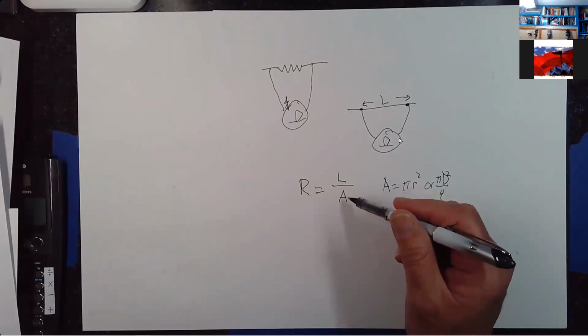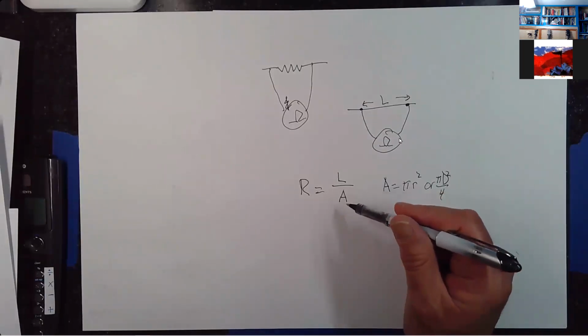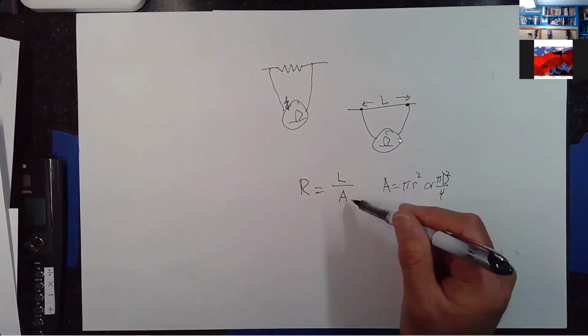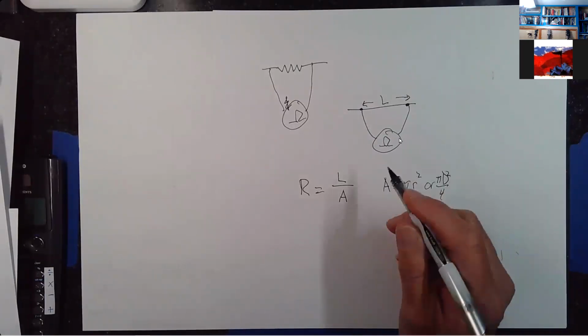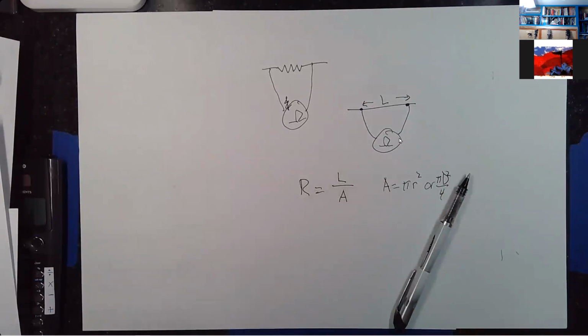This is the reason that they make wires thicker and thicker. If you've got 14 gauge wire in your house, for instance, that's a particular diameter. 12 gauge wire is a quite thicker diameter, harder to bend those 12 gauge copper wires.